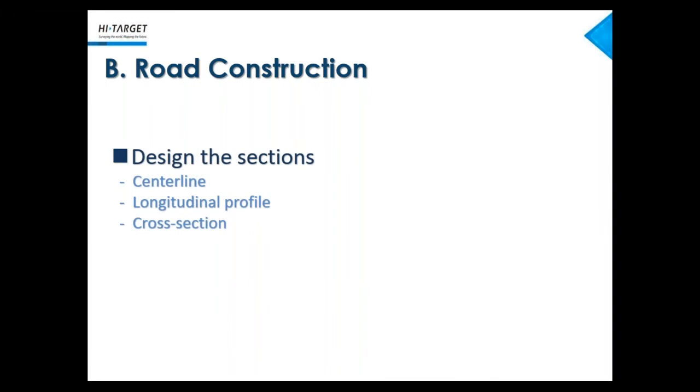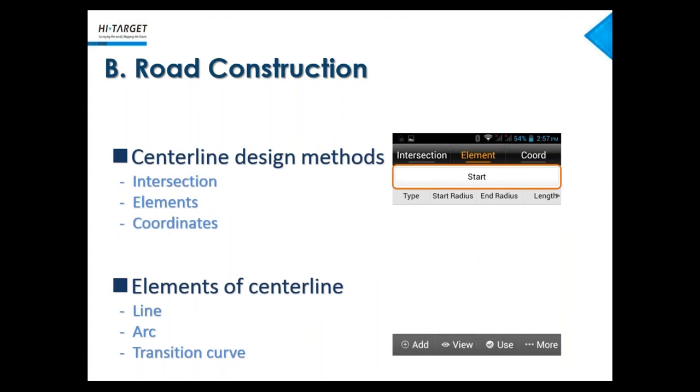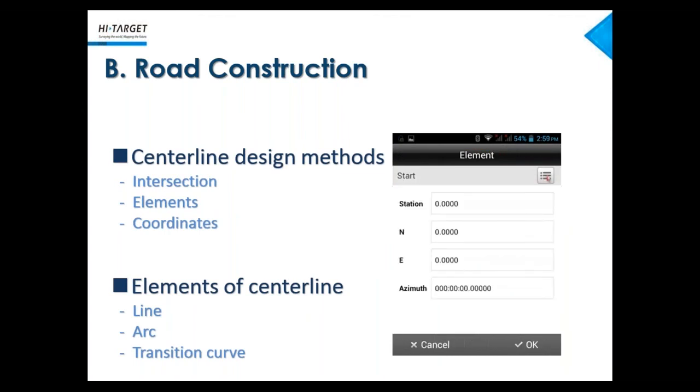So that means you will collect the points where we are going to make the road, to collect the current cross section. How does it look? And then the app will compare it with the files in the app, coming from the profile and the cross section. It will give you the results, how much you need to cut and how much you need to fill. And also, like I mentioned, there are two methods here: one is the average method, the second is the pyramid method.